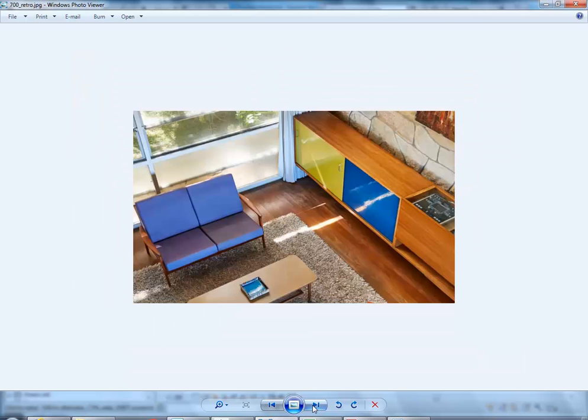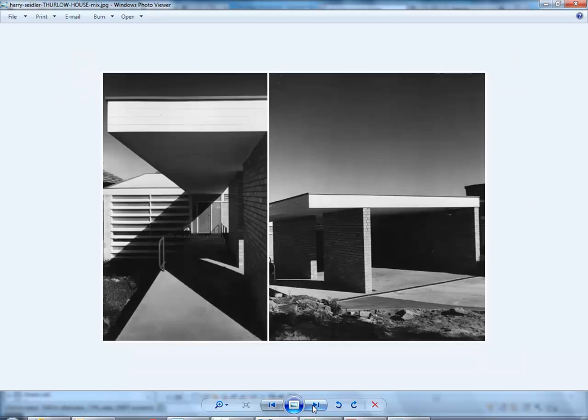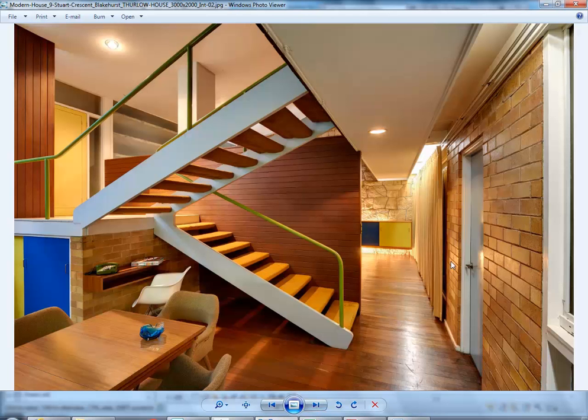I'm just going to see if you had that other photo that had the bricks here. So I just want to check that. Well, we don't even need to, because here you can see you've got the door. So what's standard door height? Exactly, 2100. And then you've got 1, 2, 3, 4, a few bricks above that, which would be about 300 altogether. And so that's 2400. I'd say almost definitely, with a bit of a bulkhead coming down. So it would be less than 2400, which you couldn't do these days.